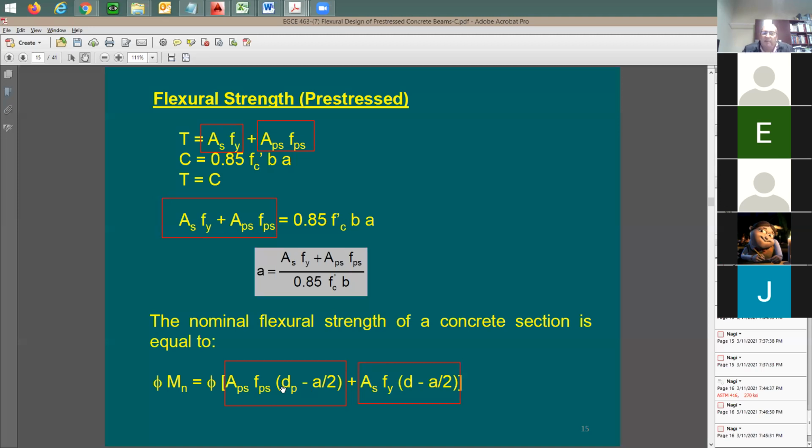And then you come later, you apply the full pre-stress force. So some strands are going to be tensioned, some strands are just left for now. And this is usually the case in bridges. In big bridges, they do it this way. They do partial pre-stress at the beginning, just so that it's going to be supporting itself. And then later on, they apply the full pre-stress force. So it depends on the design. You have more control here on the phases and the loading stages, if you like to call it this way. You're going to be controlling exactly how much pre-stress force you apply at what time of the loading schedule and staging.